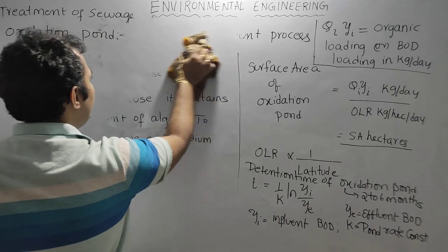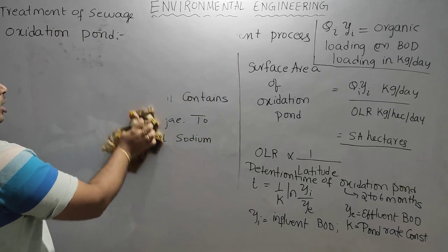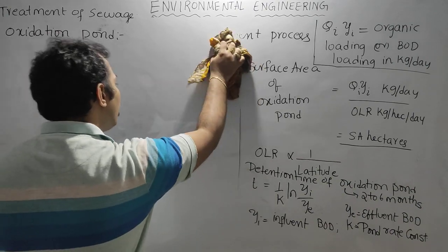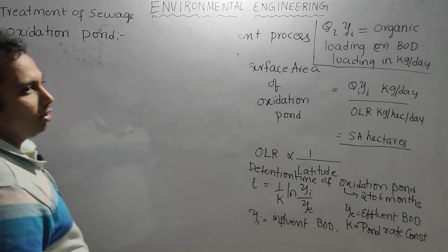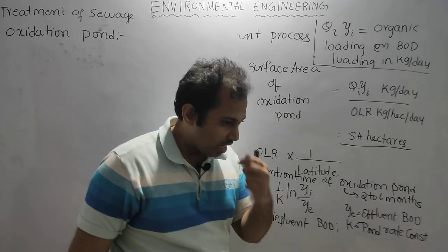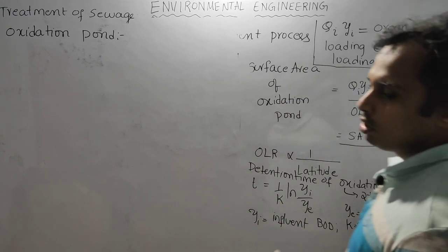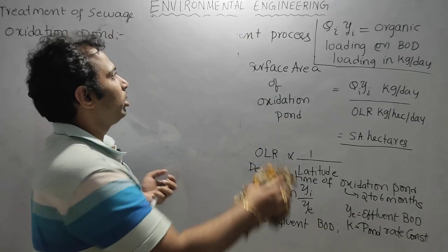We keep all the sludge in a kind of pond and leave it. It may be an aerated lagoon or a non-aerated lagoon. After some time, whatever organic matter is present inside the lagoon will naturally convert into manure, which will be used for plant growth. Those are nothing but lagoons.